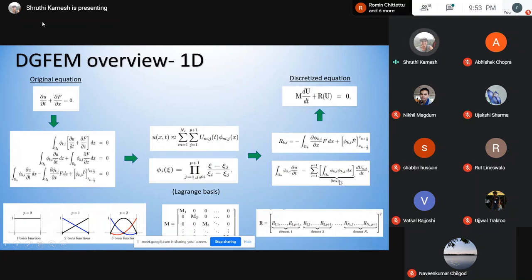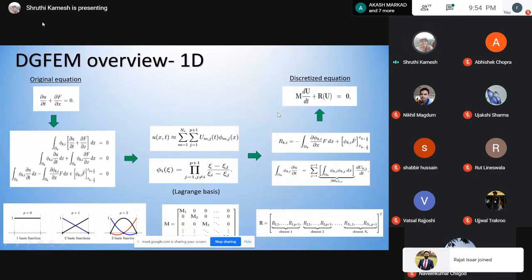So each element has its own M_k_ij, that is, each element has its own mass matrix over here, if you can see this. M1 refers to the mass matrix of element 1, element 2, and so on, up to element N. What it means is that it refers to the physical contribution, the presence of each node. If I have p plus one nodes within an element, each one has a separate contribution as a result of its existence, right? And that is why I have that mass matrix.